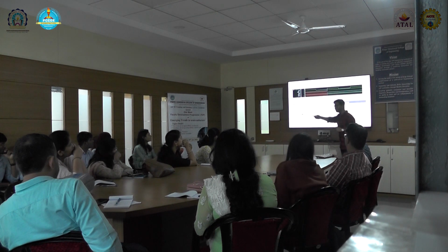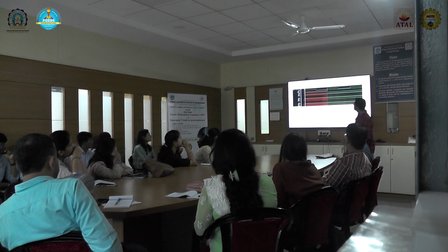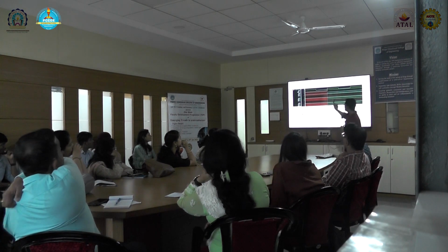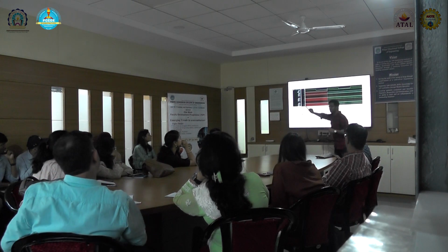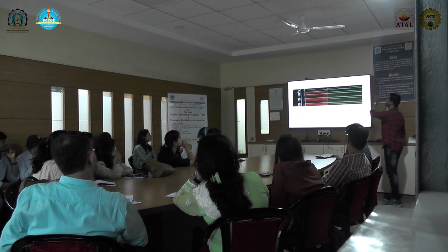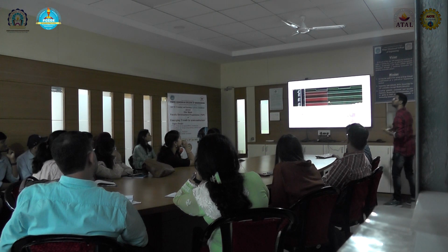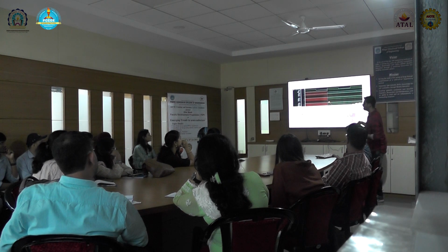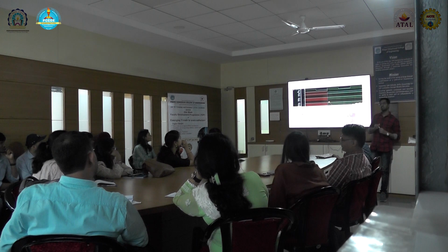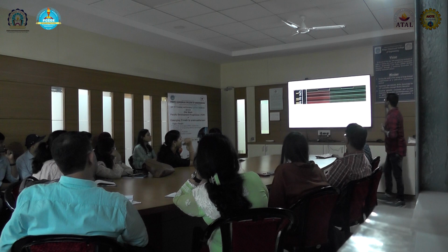So let's see why this done got asserted. We will add all the signals in formal to check what happened. As you can see here, rec1 is not there, rec2 is also not there, but we are getting done 1 and done 2. Done 1 and done 2 are inputs to our DUT, so we need to control our inputs. How are we going to control our inputs? As I said, in formal we don't provide inputs from a test bench, but we are seeing that inputs are not behaving as we expected. So how do we control them? Constraints, correct. We are going to write constraints.